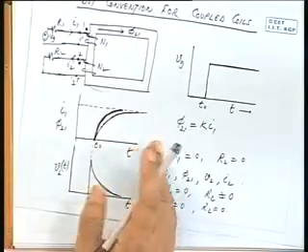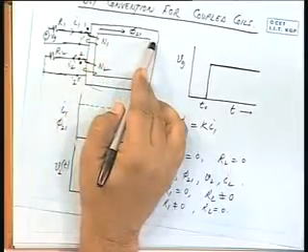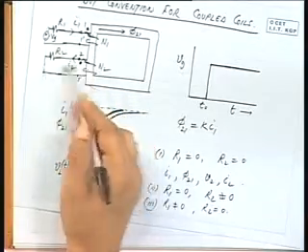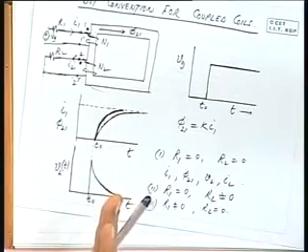That is, across an inductance, if I switch on a supply as a DC voltage, pure inductance, there is no resistance, what happens to the current? It is L di by dt, which is constant, V. That means I will be constantly increasing. It is proportional to integral V dt. So you will get a current that is continuously increasing, and that will cause a secondary current also in the reverse direction that will also be constantly increasing. So both primary and secondary currents will be increasing continuously.